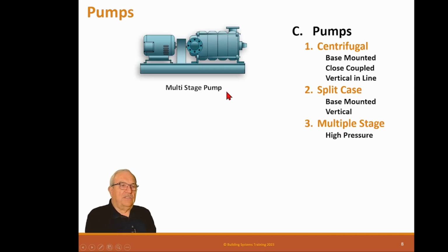Now these are specialty pumps. This is a multiple stage high pressure pump. If you need really high pressure, you can get a pump with lots of stages. I've seen these up to 8 or 9 or 10 stages. The biggest one I ever did was a mine where we had to pump the water 1,500 feet, and it was an 11 stage centrifugal pump.